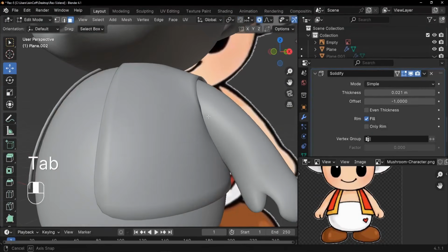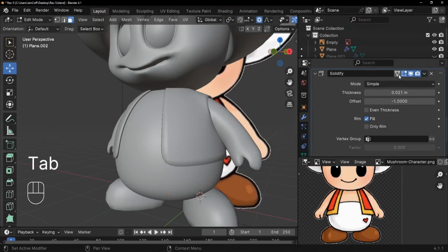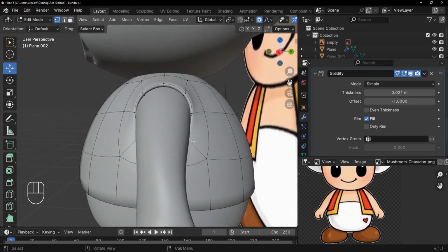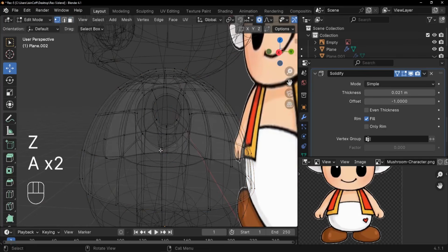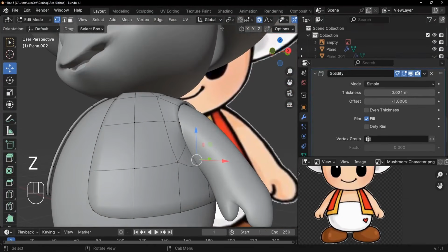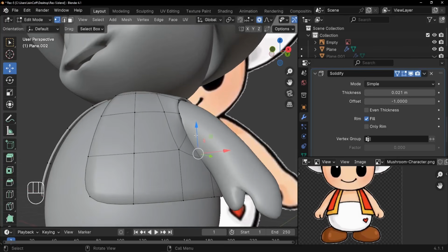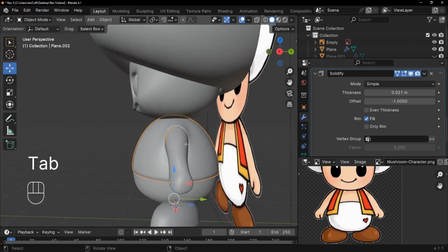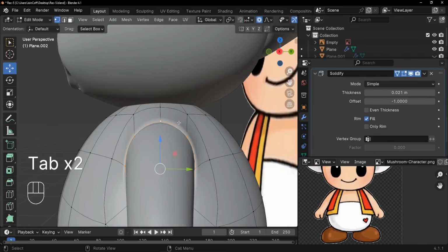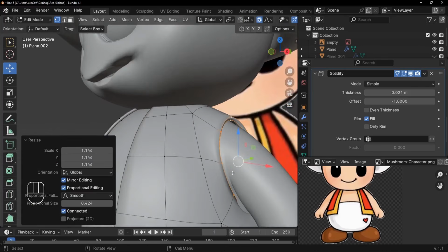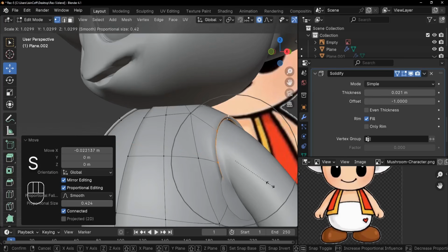Something like that. Here for the bottom, let me check again the on cage. Let me select the bottom, and switch to wireframe so that we can grab the bottom. Okay. And we can move it down with the proportional editing tool enabled. So let's just take it down like this. But I prefer here to scale this part. We can press Alt, try to scale it a little bit up. Scale it up like this.